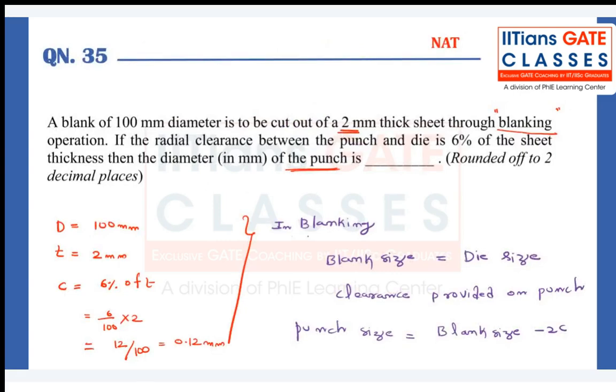So in blanking and punching, I told you, in punching, punch size equals hole size. Now die size equals punch size plus 2c. Now here it is minus 2c. That's it. Only very simple. So how simple it is? One more question solved. Yeah, great. Now let us move to another question.